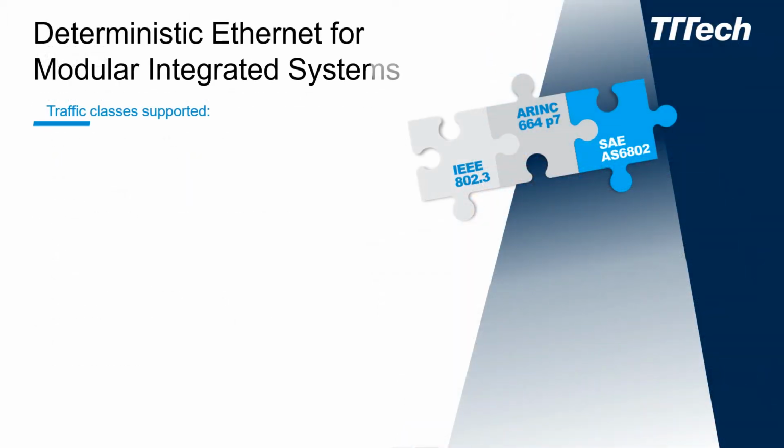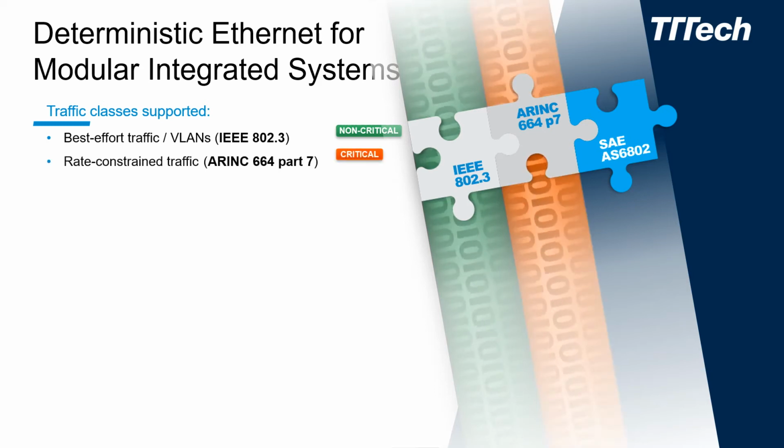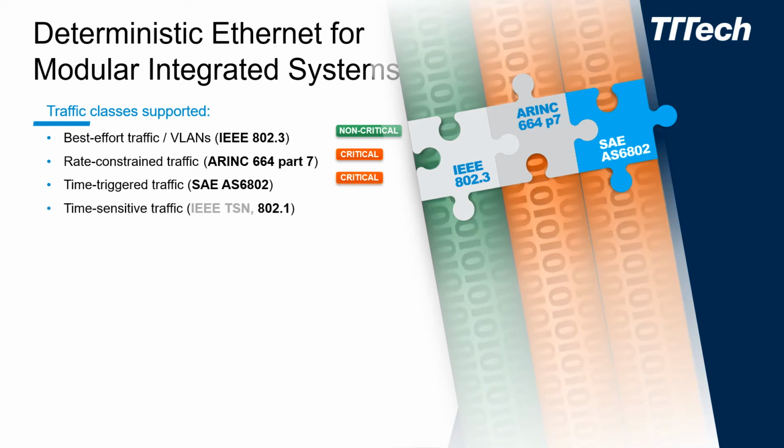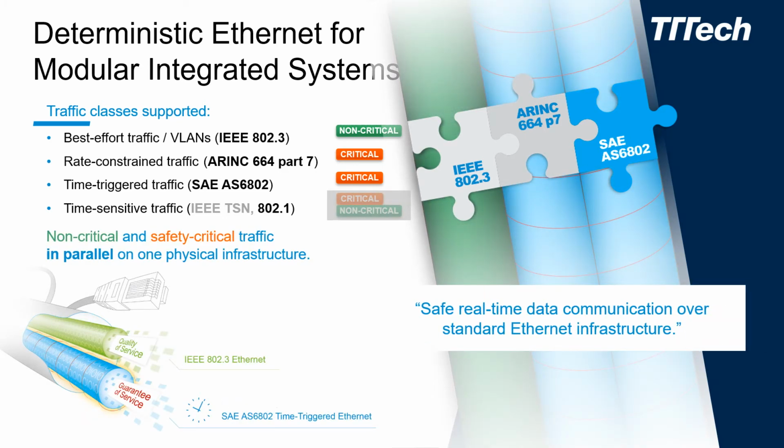So, deterministic Ethernet supports modular integrated systems by having best effort traffic, standard Ethernet traffic for example, also supporting VLANs, rate constrained traffic as defined in ARINC 664 Part 7 for critical traffic, and then time triggered traffic, which can be used for both critical and non-critical traffic, as well as, in the future, time sensitive traffic according to IEEE TSN standards, which again can be used for critical and non-critical traffic.